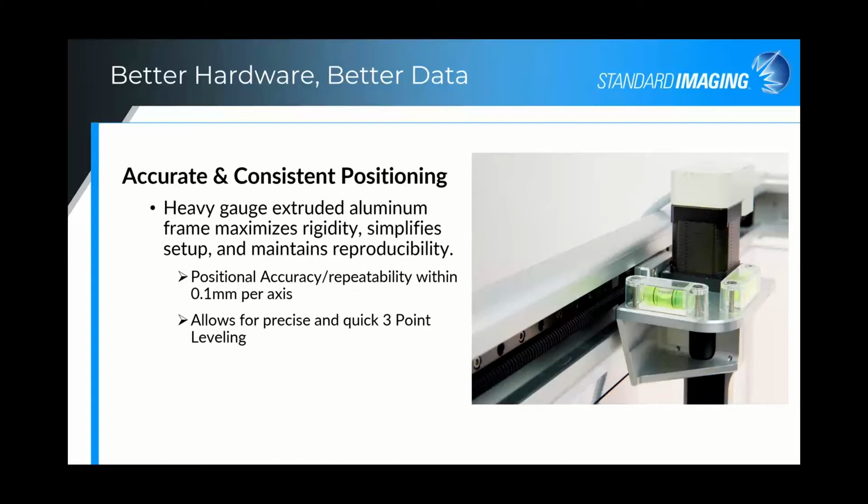It's a manual setup, and we looked into what's existing out there as far as automatic leveling, and we've played around with some of our own internally, and there's still the tried and true 3-point leveling. The way our system is set up, you can do it just as quick with our 3-point leveling as you can, if not quicker than some of the automated ones, because with the automated ones you need to start from scratch if you don't quite get there and your runouts are not level. This way you have the ability to do very minor tweaks as you do your leveling.